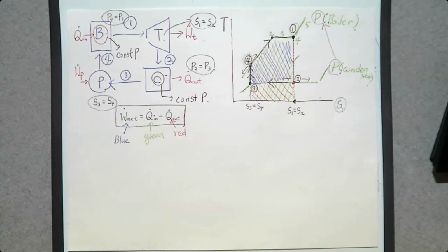So the simplest way we can do is, can you control this entropy? Can you increase or decrease? Sounds pretty difficult, right? So controlling entropy may be slightly difficult. What about another property? Pressure. Can you increase or decrease? Sounds simpler than changing entropy. So let's think about that. How many pressure values do we have? 1 and 2. So let's look at each one by one.